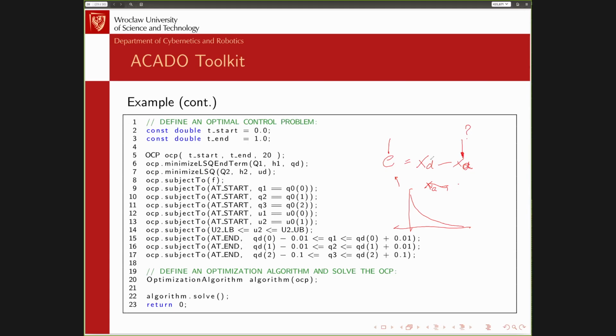You don't have this information all the time, or the frequency at which you get this information is different from the frequency of the controller, because you need to know that this control should work at high frequency, right? Like 100 hertz or 1 kilohertz. So these are typical frequencies at which we run this kind of stuff. So the question is how you can get this state. And in most cases, you need to estimate the state.